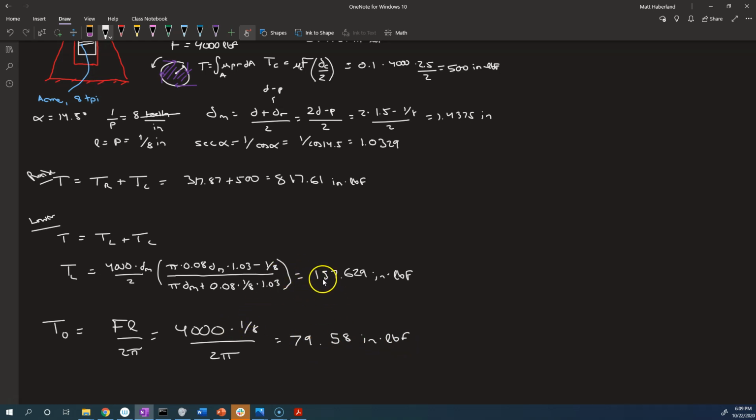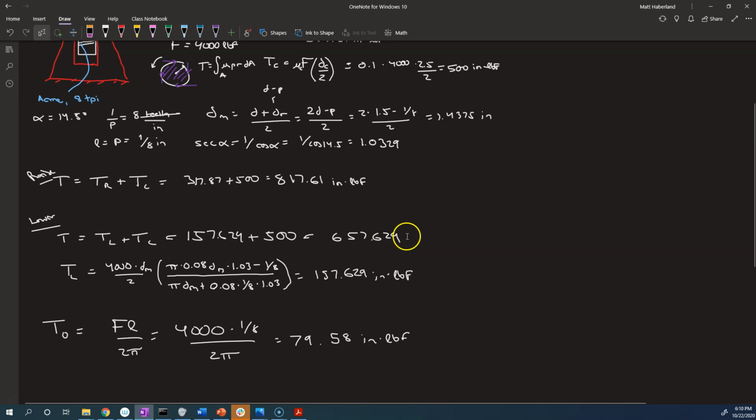See, even when we're trying to lower it, there is almost double the amount of torque that's required because of all the friction. And when we're trying to raise it, it's way, way more. Now, maybe I should have finished the lowering calculation if we want to add these two together. Oh yeah, so the torque required to lower the load, considering the collar torque, is pretty substantial and way more than the ideal torque. But we're calculating the efficiency of raising the load.